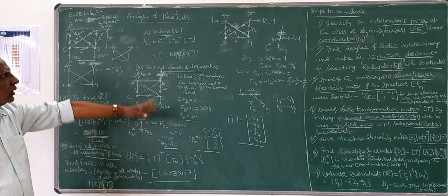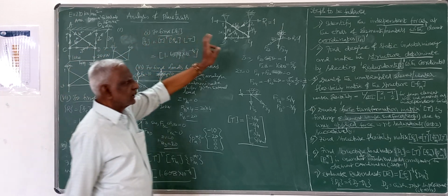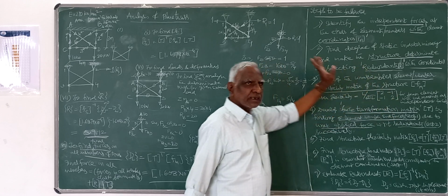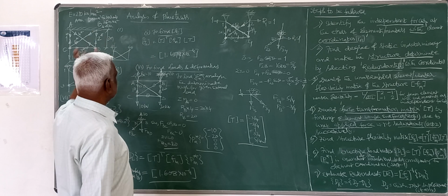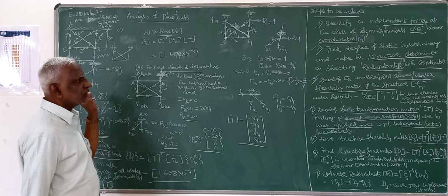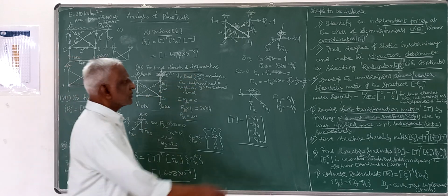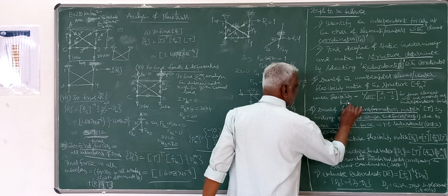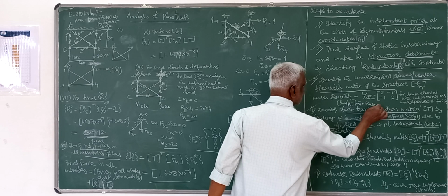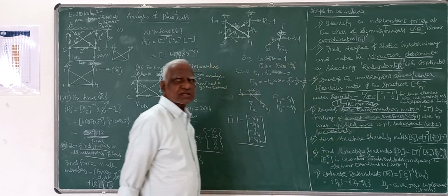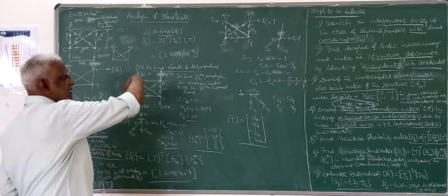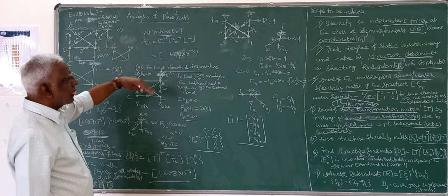Same procedure you have to follow, only the element stiffness matrix. Instead of beams, L by 6, 2 minus 1 minus 1 2 what you are taking, here we are taking it as L by AE, that's all. Only one expression that you remember. It is only L by AE. This is for truss, as element flexibility matrix. And you have to arrange a diagram, that's only one of the element. The rest are all 0. So Fm is there.